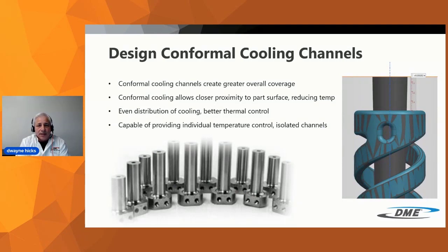I have personally spent time at the press waiting for the sprue to cool, knowing full well the part was ready to eject some time ago. These components create the ability to significantly reduce cycle time by quickly cooling the outside surface of the sprue material, allowing for a faster turnover.